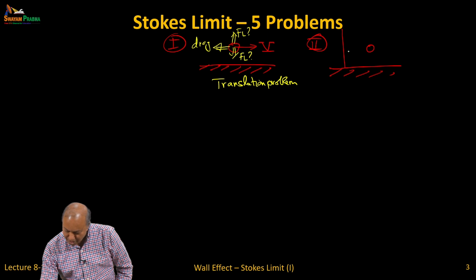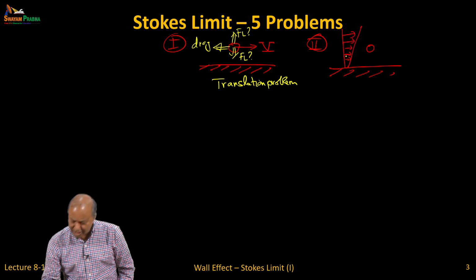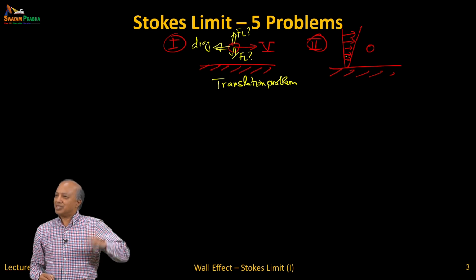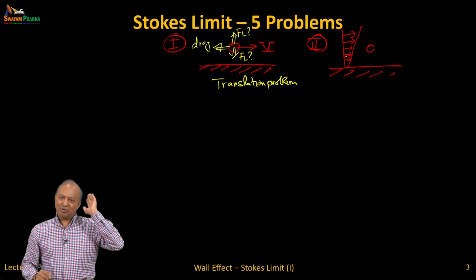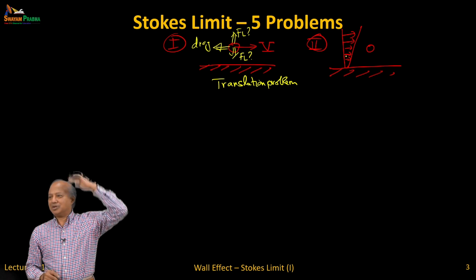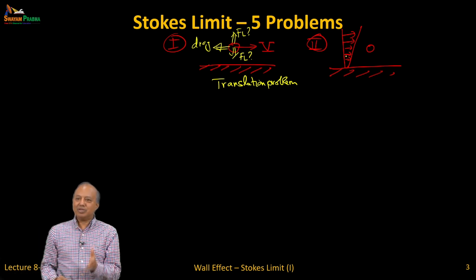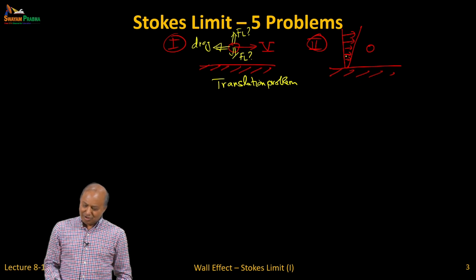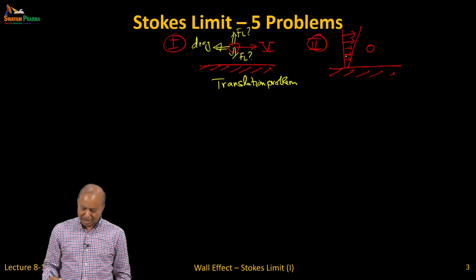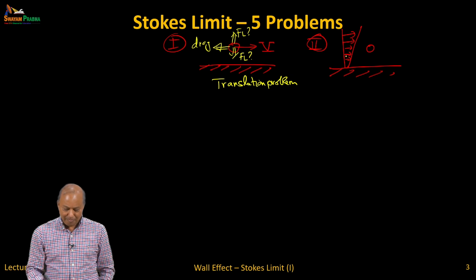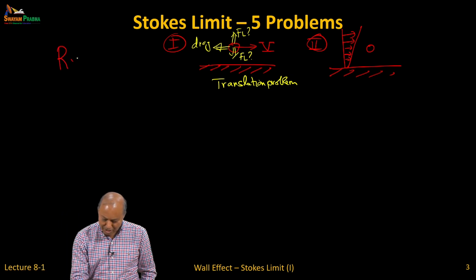A fixed particle in a shear flow. This is what I said earlier: I'm not going to consider a thin boundary layer, etc. I'm going to assume the boundary layer is much thicker than the particle. Therefore, the particle is in a linear profile, deep within the boundary layer. You can change that if you want to make the problem more complicated. All of them I'm talking about in the zero Reynolds number limit, and I'm talking about steady flow.